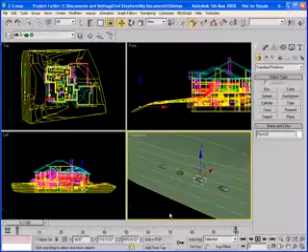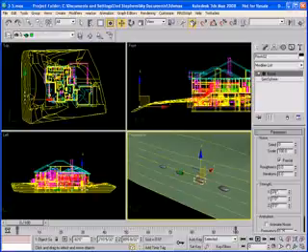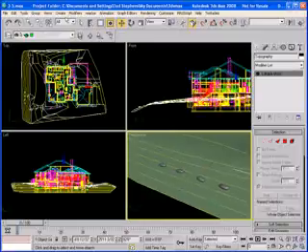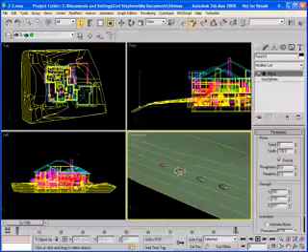If I go back to my rock 02, I want to add something to this geometry so it's a little more random. So with rock 2, I'm going to go under seed, under the parameters in the modifier, and add a seed of 1. Basically that just takes your noise distortion and randomizes it differently. Then I'll go to my next rock, which is going to be rock 3. Again, I'm going to go into the modify panel.